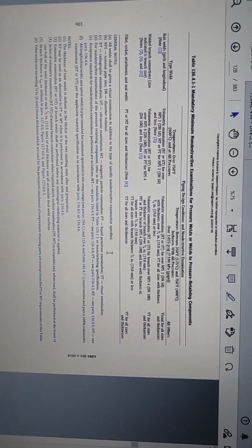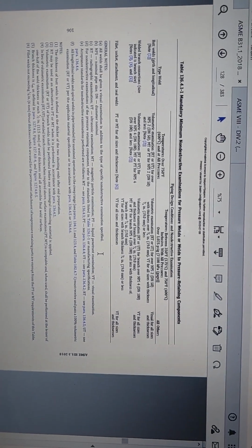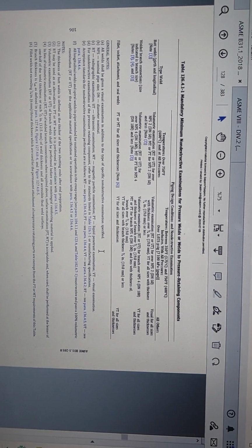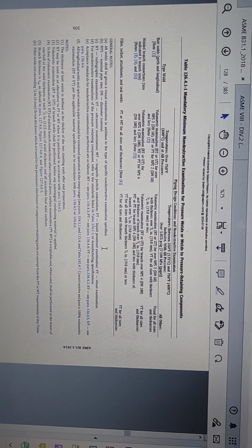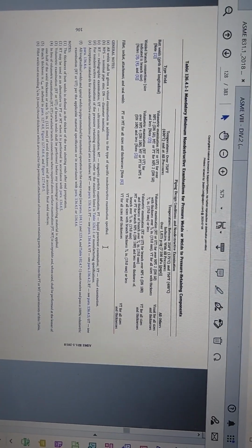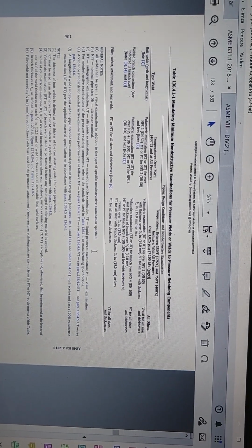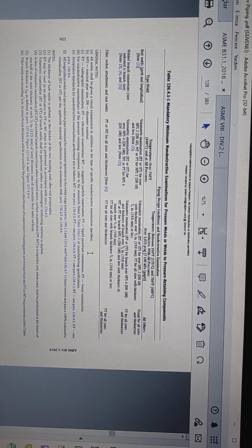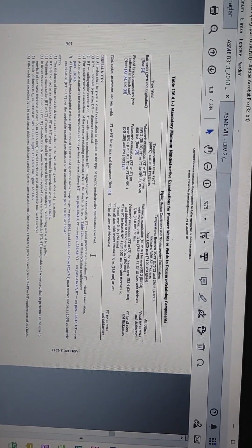According to these NDT examinations, the pipes are separated into three groups: temperature over 400 centigrade with all pressures, temperature between 175 and 400 centigrade with all pressures, and all others. And the welds are also separated into three groups: butt welds, branch connections, and fillet and socket welds.